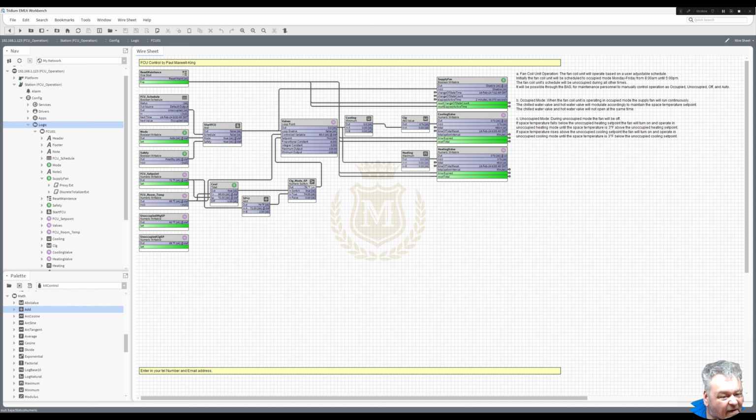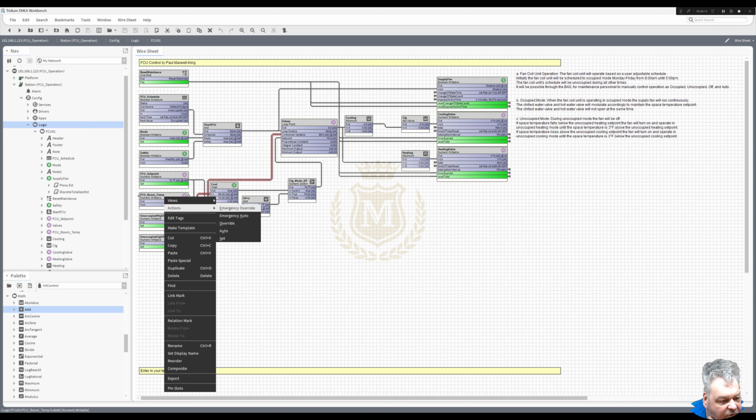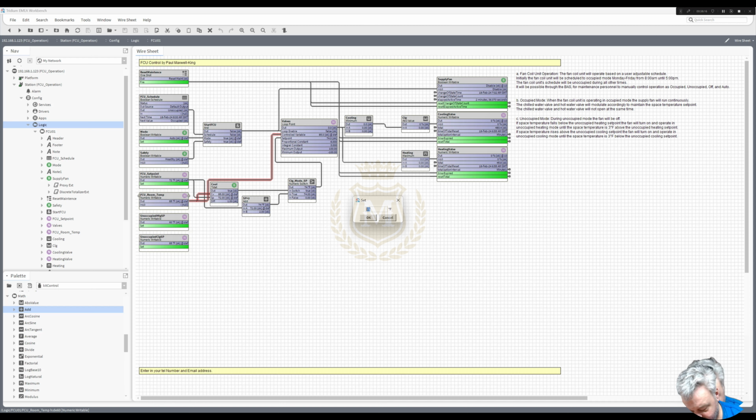And if it's going to be false, which is going to be the other way round, so let's put this now to actions set to 70 degrees. That's now false, so we're going to do a subtract. Set point -2.